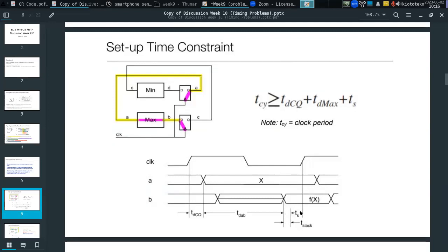And that is good, because what happens if we don't have enough time to set up the value here? For example, if we have 0 here, and we update the clock and it updates the flip-flops, and now there's a 1 here, and from here we should get a 1, but there's still this 0. If the output doesn't arrive in time, this flip-flop will still maintain whatever previous value it had and will propagate it to the other parts of the circuit, but that will be incorrect, no?